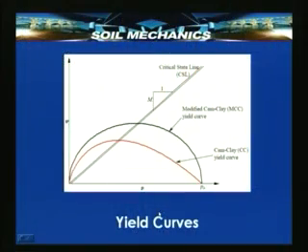Here are the yield curves which will result if we use the Cam-Clay model. Here is the yield surface on the PQ plot for Cam-Clay. This is for the modified Cam-Clay, and this is the line which tells us which are those critical stress states at which a soil will, either according to the Cam-Clay model or according to the modified Cam-Clay model, correspond to a situation where there is a yield or where there is a large deformation.